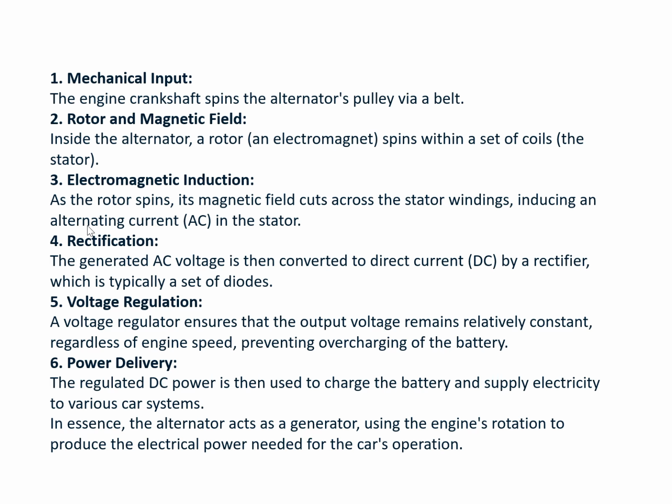Once we provide a closed circuitry to the output of the alternator, it produces the current flow through the alternator. This is called alternating current. Rectification is mainly used to provide battery charging and to supply other kinds of loads as they need DC supply. The voltage regulator ensures the output voltage remains a constant value irrespective of the speed of the engine.